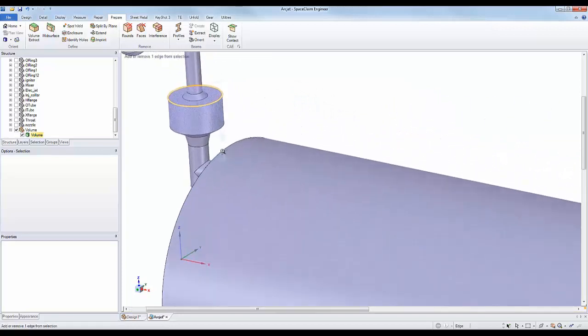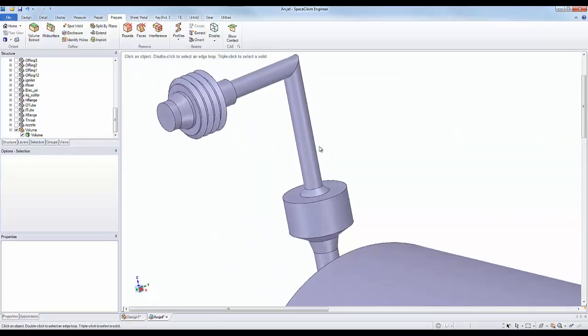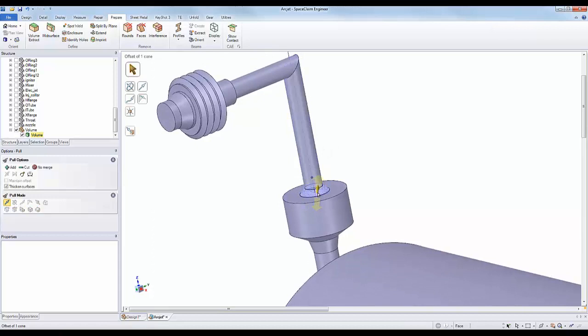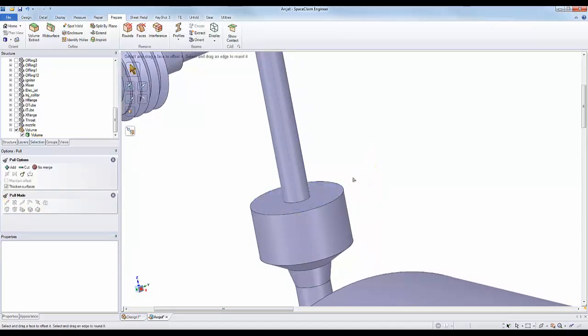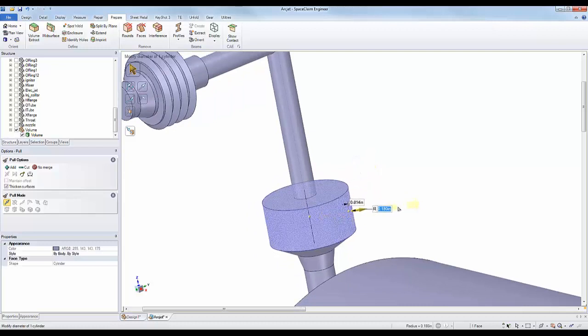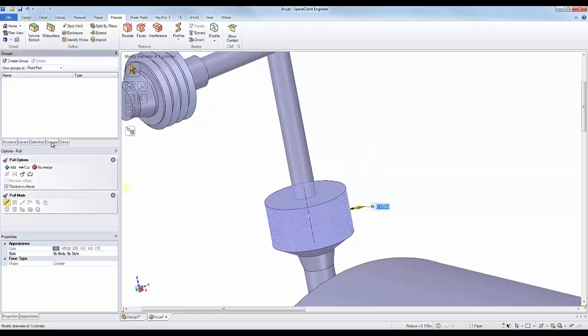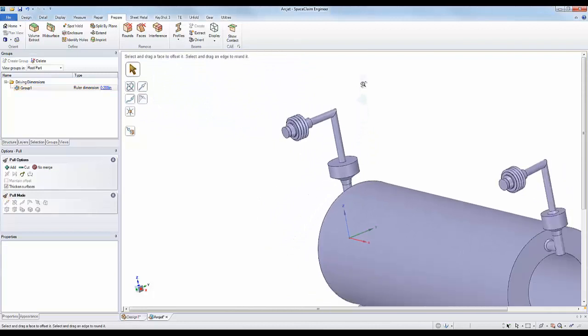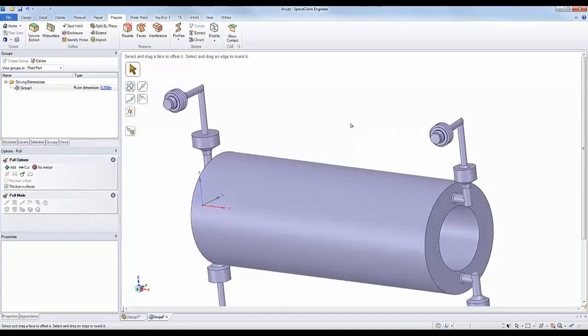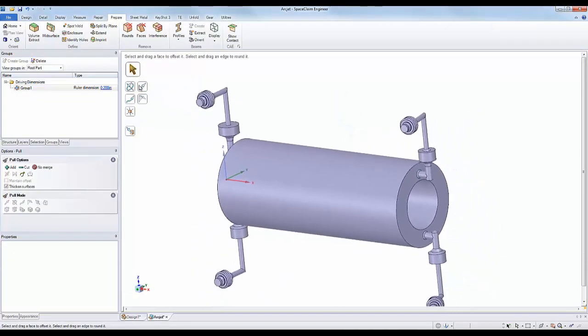internal cavity. And the thing that's great about this solid is it's just like any other solid in SpaceClaim. I can edit it directly, remove detail, change sizes, even set up a group with a driving dimension, which can be used to run an optimization study when transferred out to another piece of software like ANSYS or COMSOL.